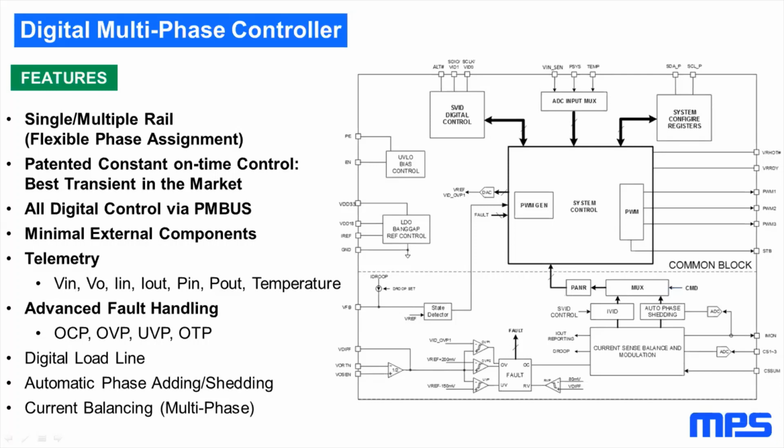Input and output voltage, output current, and temperature measurements are supported in all of our devices. Input current or power measurement requires an external device that does the measurement. But quite often a charger is used that automatically determines the current or the power. Some controllers also have a specific amplifier implemented that allows adding an external shunt resistor to measure the input current, but this depends on the controller.